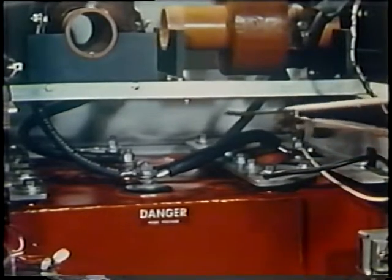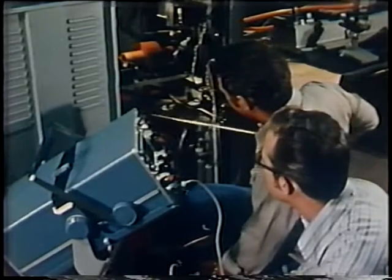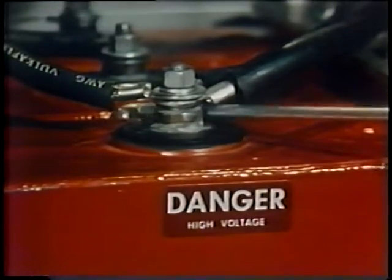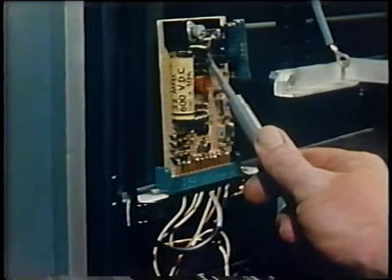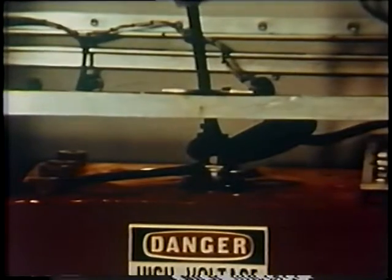Because of this danger, maintenance should be performed by two individuals, since several manual operations may have to be handled simultaneously. To make certain it is safe to work inside, all high voltage points must be grounded and remain grounded. This will dissipate any stored charge remaining in the capacitor. This demonstration shows what may happen if it remains charged.